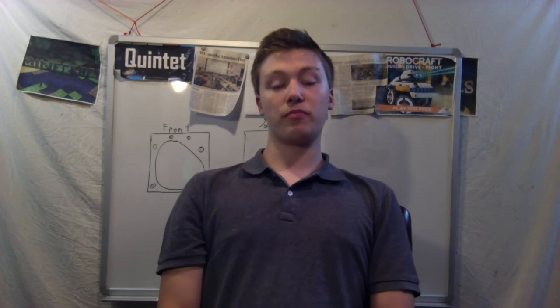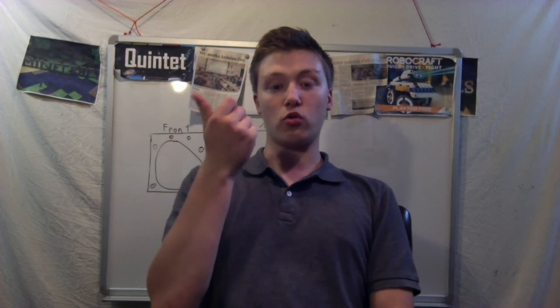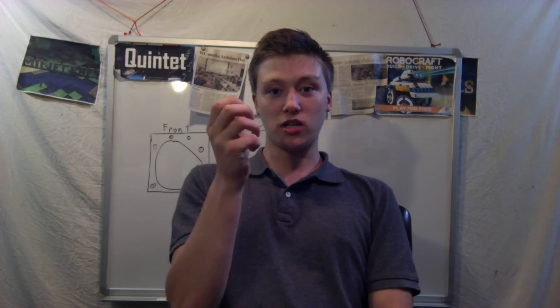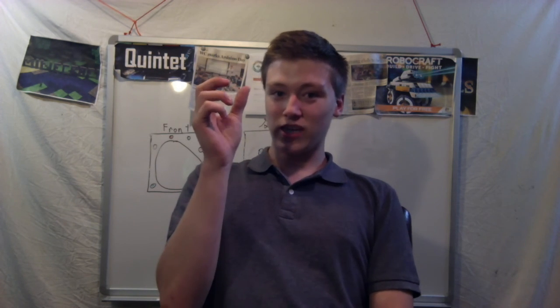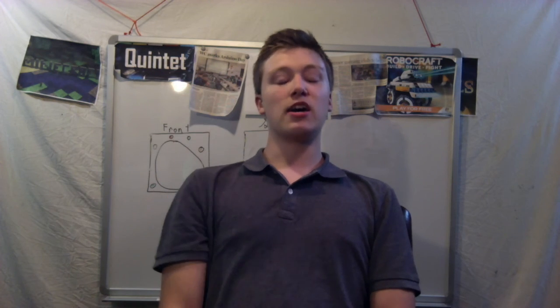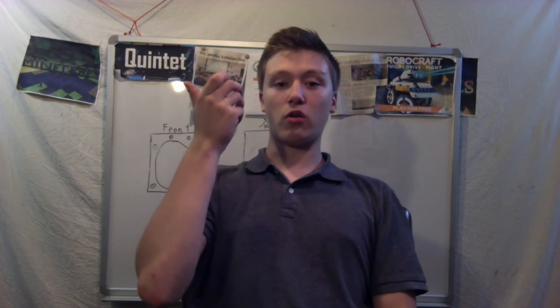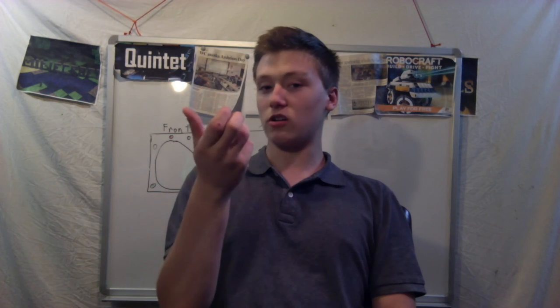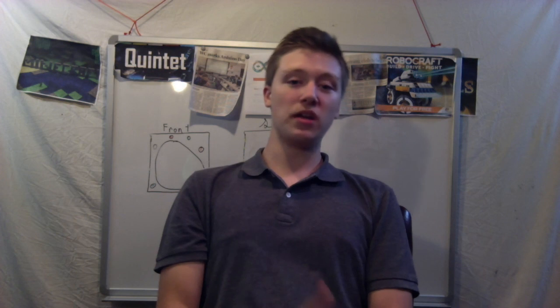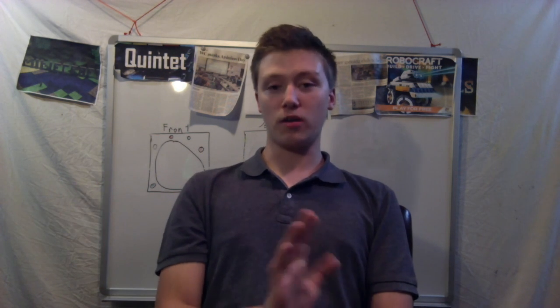Like a servo, because a servo isn't all the way on or all the way off. It's got all these tiny little turns, right? You can turn it just tiny, 6 degrees, 2 degrees, 3 degrees. That would be an idea of an analog device, because it's not Boolean, it's not on or off. It's got turns, tiny little degrees. So since we really don't use analog write, there's the PWM pins for that. So hopefully that makes sense. You'll understand why I was talking about all the PWM pins, and we'll get into that at a future date.